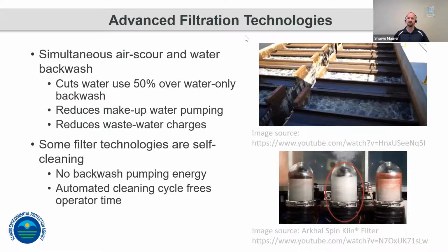So maybe this is a pre-filter system that extends the life of your regular sand filters. But there are these technologies available out there that are starting to permeate into the market, particularly for older plants that are looking at filter replacements for entire systems or filter media replacements. Maybe it's time to also look at whether there is a way to extend the life of those, so you reduce your long-term costs by adding in a pre-filter system or a new type of filtration control technology.